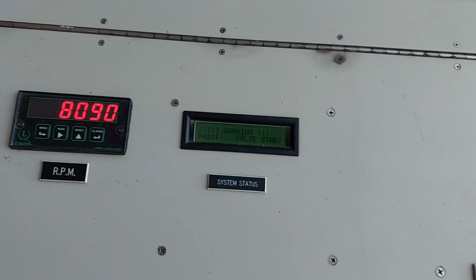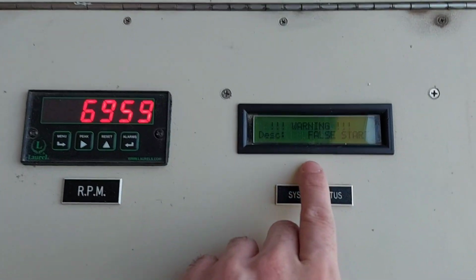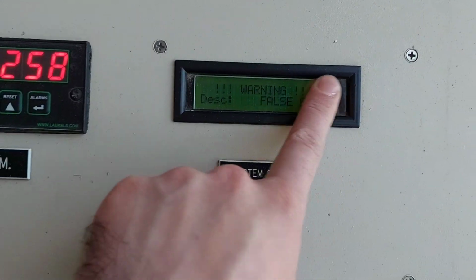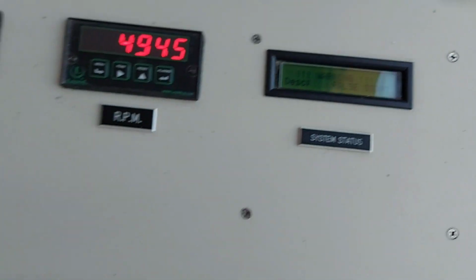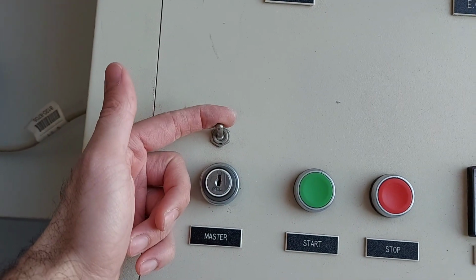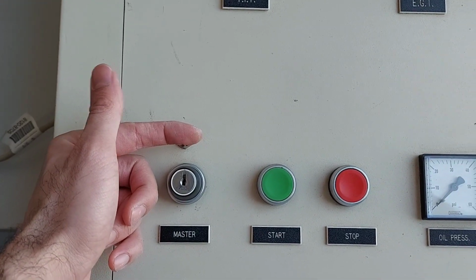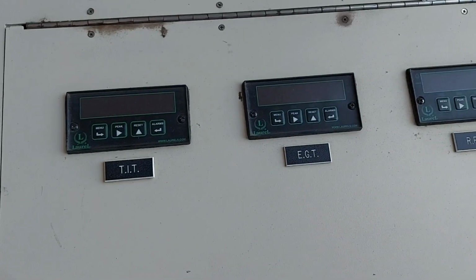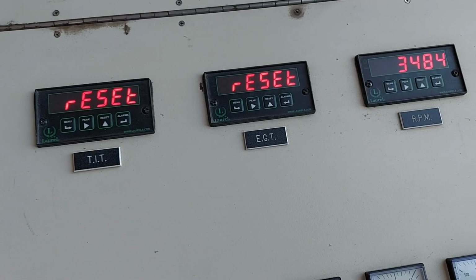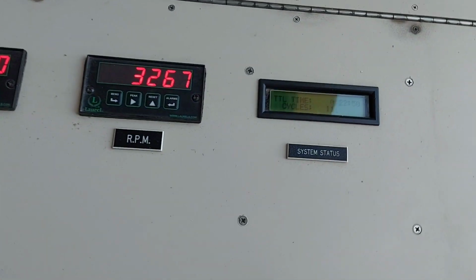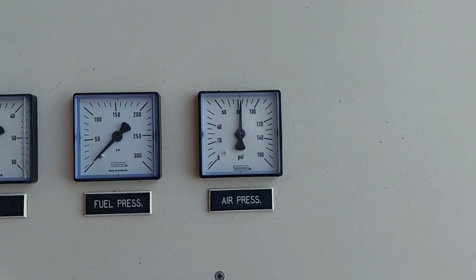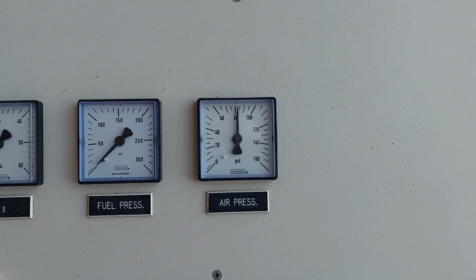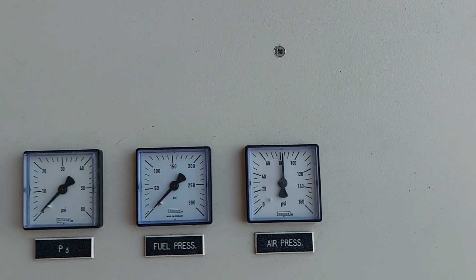You may have a false start at the beginning. That's completely normal at this stage. What you need to do if you get the false start is to switch off the simulator, switch it back on again to restart the system, ensure that the supply of pressure is returned, and then try it again.